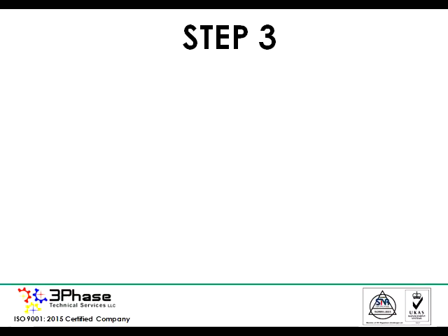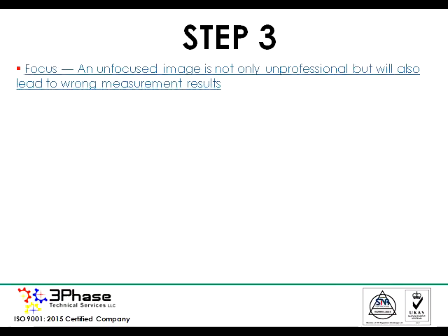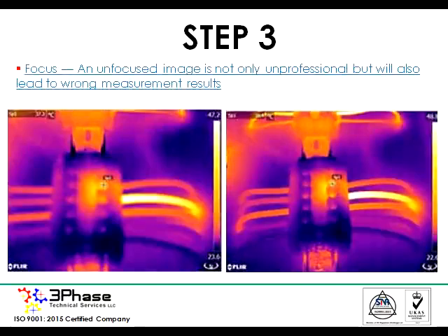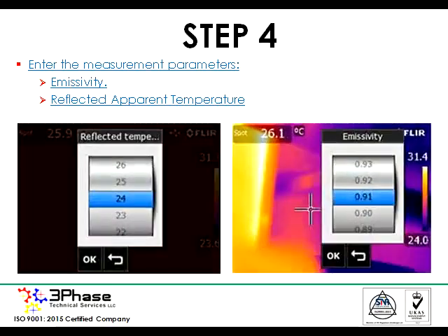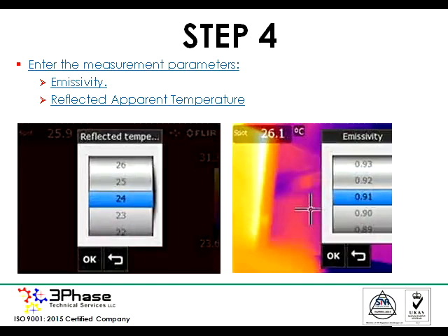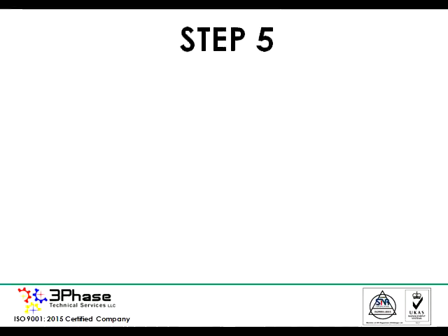Step 3. Focus. An unfocused image is not only unprofessional but will also lead to wrong measurement results. Step 4. Enter the measurement parameters: emissivity, reflected apparent temperature. Step 5. Save the thermal image and the visible images.